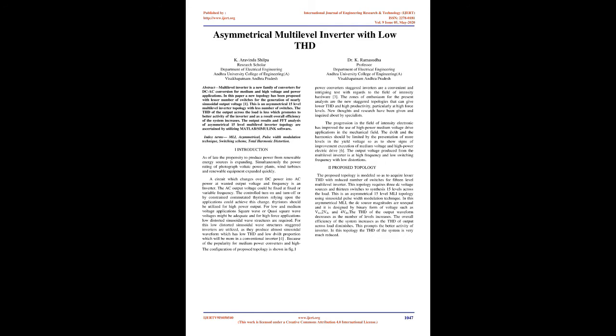The THD of the output across the load is less, which promotes better operation of the inverter, and as a result the overall efficiency of the system increases. The output results and FFT analysis of the asymmetrical 15-level multilevel inverter topology are ascertained by utilizing MATLAB/SIMULINK software. Index terms: MLI, asymmetrical, pulse width modulation technique, switching scheme, total harmonic distortion.